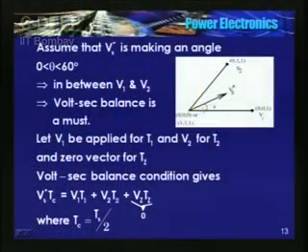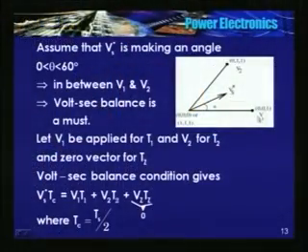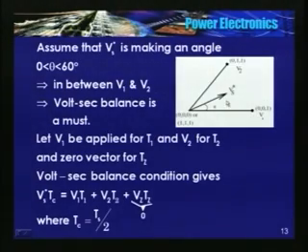Okay, I will give an example. Assume that Vs star, I put a star here because the magnitude is very small compared to the VDC, because depending upon V by F, or depending upon the frequency of the space vector, the magnitude also changes in order to keep V by F constant.